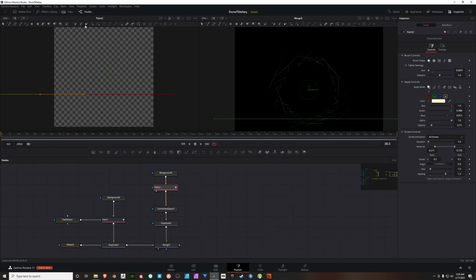That will allow me to select these points. And then if you click this tab here, it'll select all the points on that line. And then just holding down Shift, if I start to move this up, you should see on the right hand side of this screen that this is going to increase the diameter of that circle. So I'm going to keep it relatively right here for right now. We may have to adjust it a little bit later, but for right now we'll just keep it right around that point.